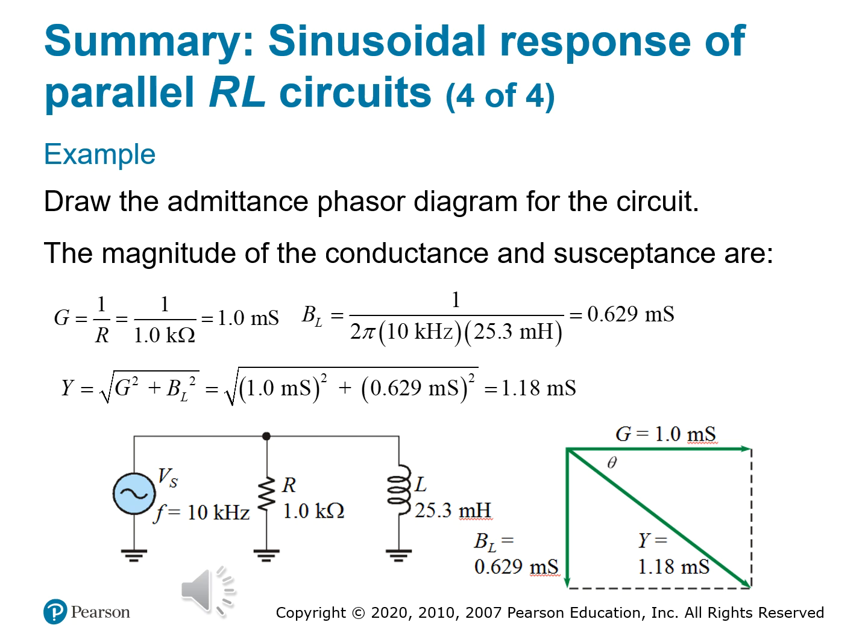And that's angled down and right. And this tells you everything: how much current the circuit draws at 10 kilohertz, how much of it is in phase, which is real, and how much is out of phase, which is reactive, and how your system is performing across frequencies. So this technique is good for high frequency analog design, AC load analysis, or anytime you want to solve parallel circuits with reactive components.